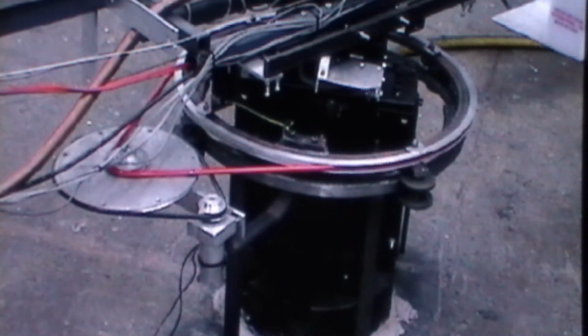The 0.5 metre diameter 4-wheel circular carriage is mounted on a similar diameter monorail and is belt driven. Two 2mm diameter nylon cords connect each side of the carriage to 2 thin spring steel plates, which are linked together by a steel bar in appropriately sized spaces. A steel plate attached to the top platform of the bearing tube at 2 points on either side of the platform connects to the link bar. There's no other connection.